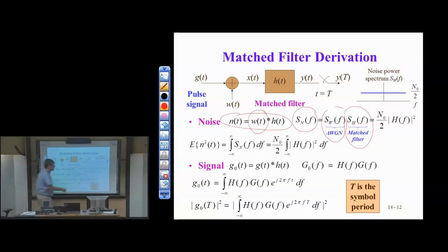What we get out of this is the variance of the noise, sigma squared, times the magnitude response squared of the match filter, which we haven't defined yet, but we're going to just have it as a placeholder. And then the average noise power we can compute either in the time domain or the frequency domain. So we use Parseval's theorem. We've talked about this before.